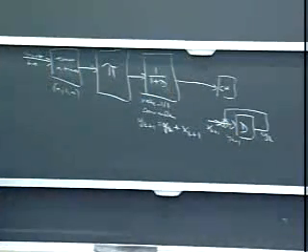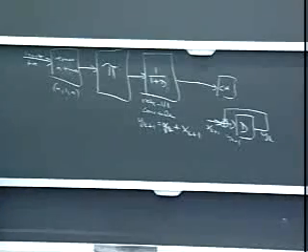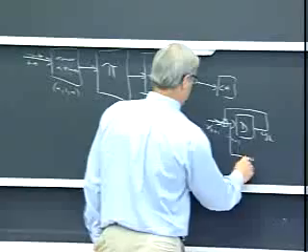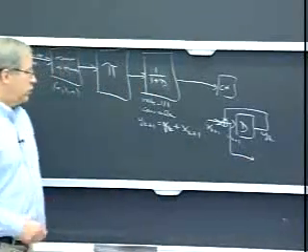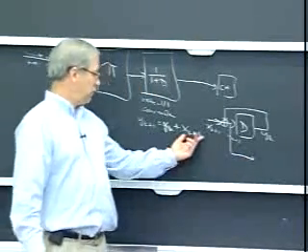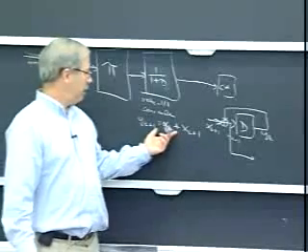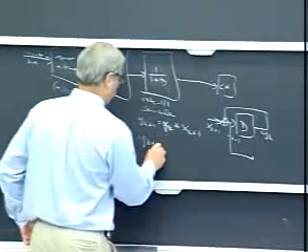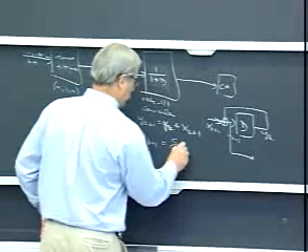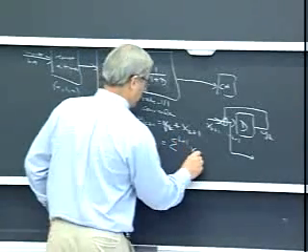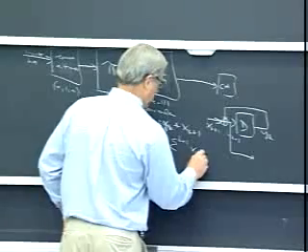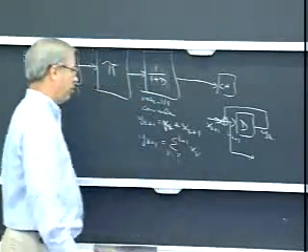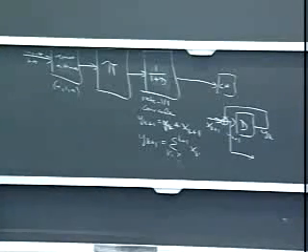Okay, so it's a very simple rate 1 convolutional encoder with feedback, where we take this as the output. It's called an accumulator because if you look at it, what is y_k doing? You can show that y_{k+1} is simply the sum, up to k+1, of all the x_{k'}, where k' runs from whatever it starts at up through k+1.